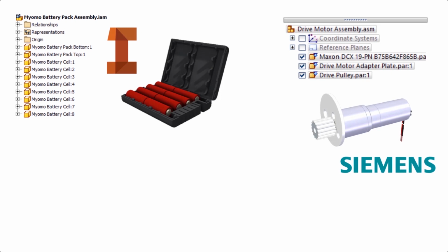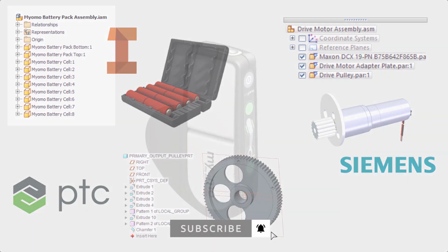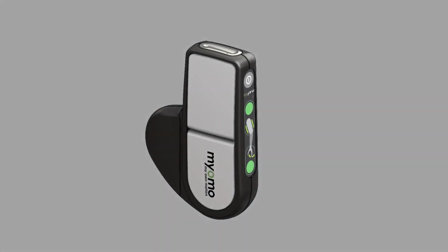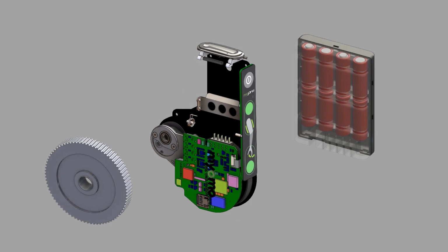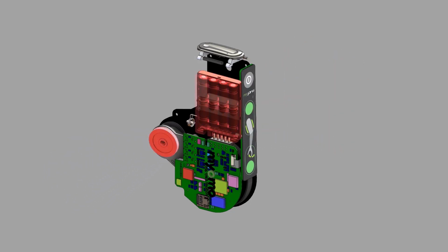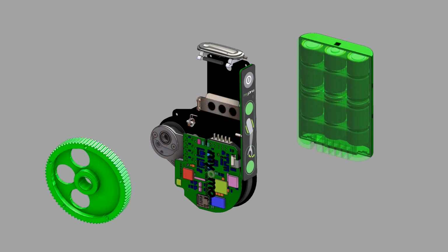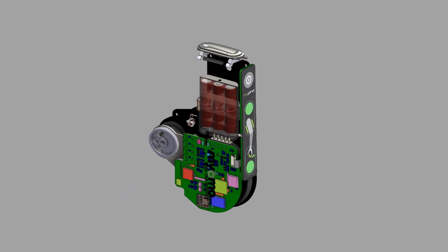3D Interconnect is much more than just file translation. In fact, it virtually bypasses the entire translation process and allows you to work with CAD data from a variety of sources as though they were native SOLIDWORKS files. It's also intelligent and understands when third-party CAD data is changed within its native design environment. By honouring face and edge IDs, changes to these files are like other changes you would make in SOLIDWORKS.